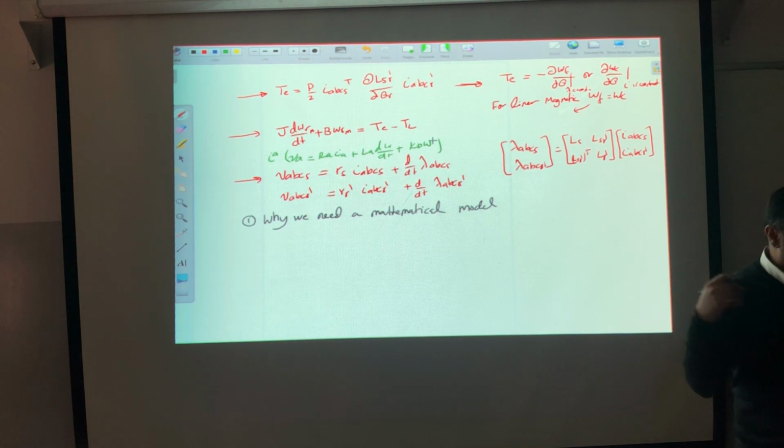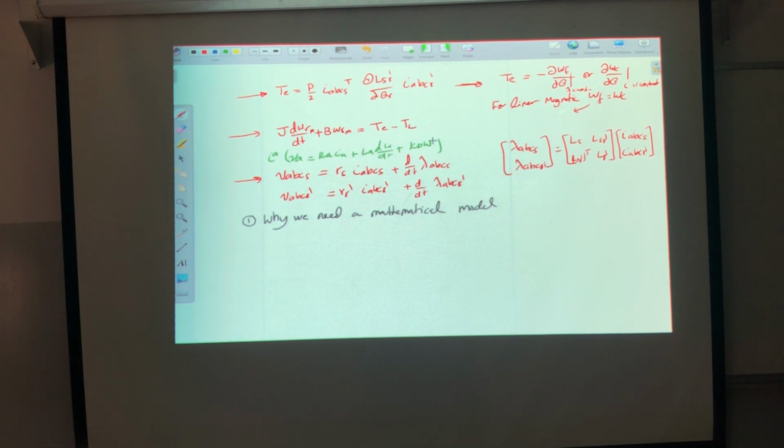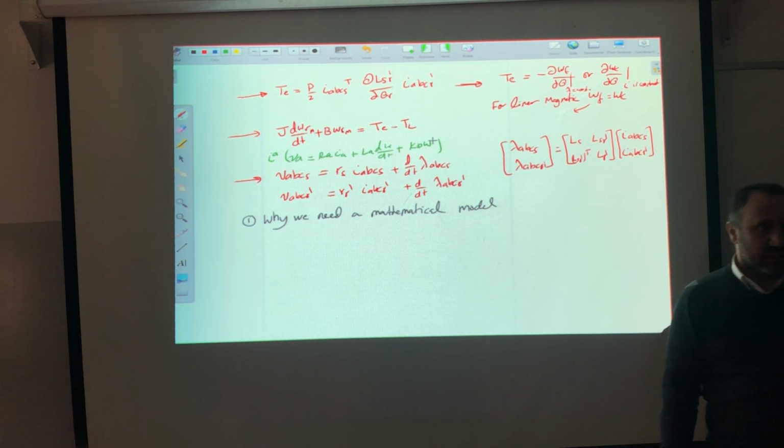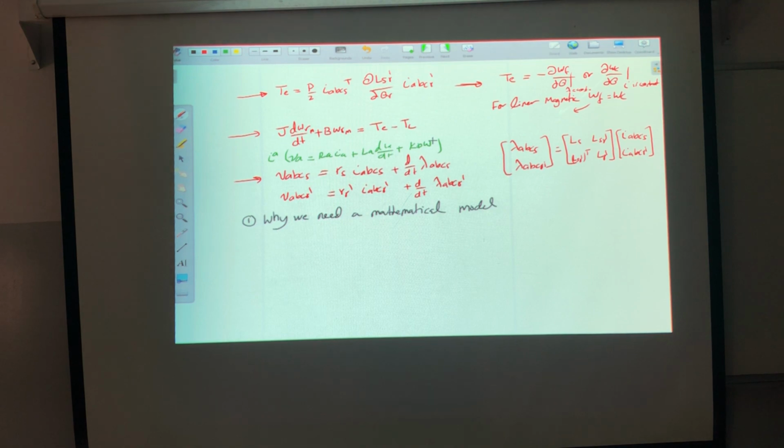So this converted power will be I K phi omega, correct? If I divide it by omega, I will get K phi I, which is the torque. See how simple that is? Now, we need to do the same thing for the induction machine.